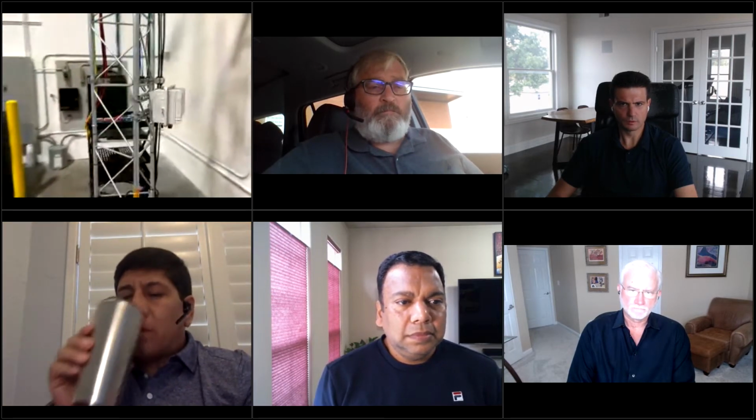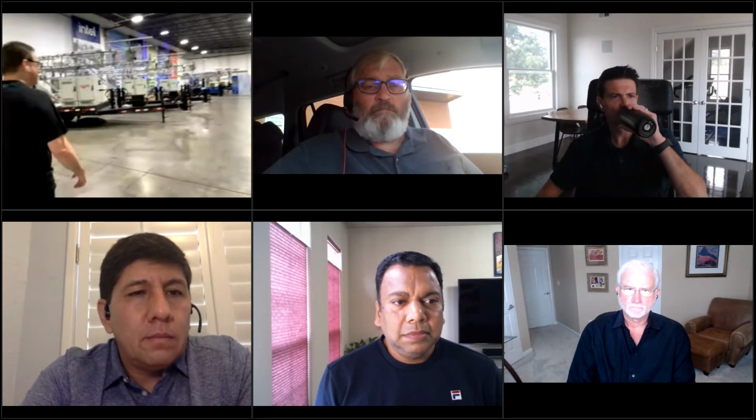So this is one of our towers where we put connectivity. On the right-hand side, you can see our Nokia Pico cell for our NDAC private network. Left-hand side is a Cambium AP for Wi-Fi 6. At the top, there's also a Cambium cnWave. That's basically a 60 gigahertz wireless backhaul that we're running here in the facility. As you come down on the bottom, we're also giving you an example of an outdoor private network antenna. This is a little bit larger, obviously higher power, and a little bit more robust for outdoors. So again, we're trying to show real world use cases of connectivity. There's also a tower in the back with very similar technology mounted on it.